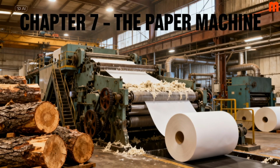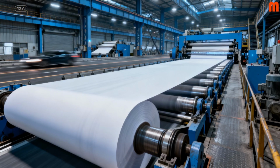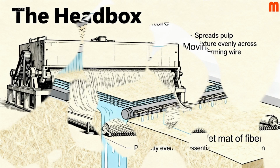Chapter 7. The Paper Machine. Now comes the most spectacular part of the process. Modern paper machines can be over 100 meters long, producing paper at speeds faster than a car on the highway. 1. The head box. The headbox spreads the pulp mixture evenly across the forming wire. A perfectly even flow is essential for good formation.